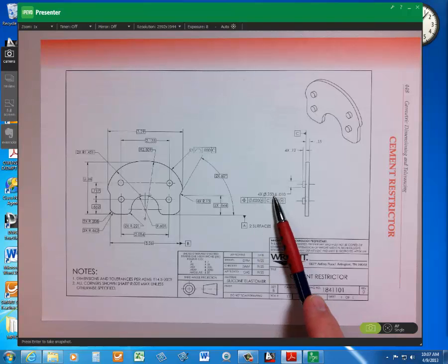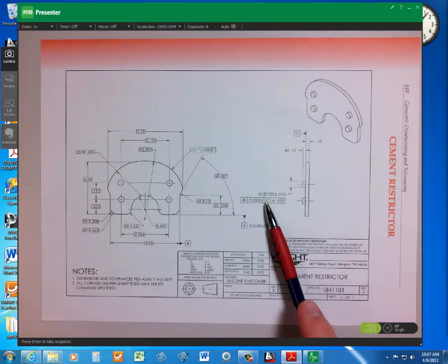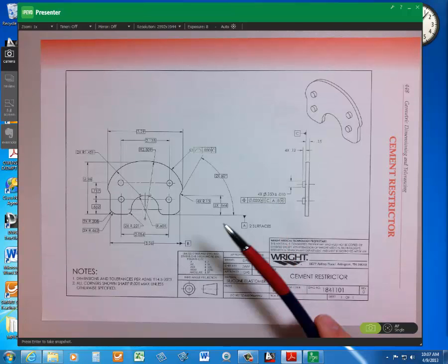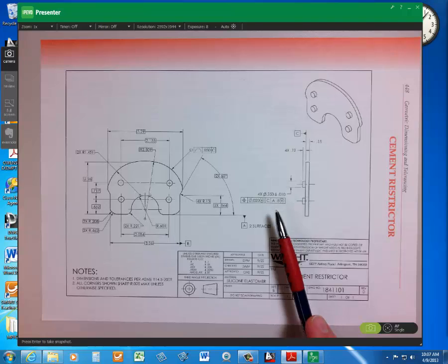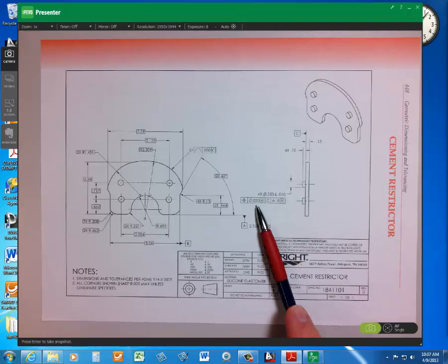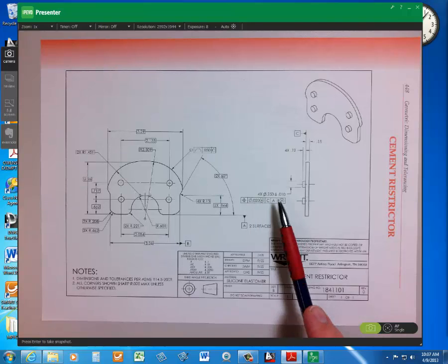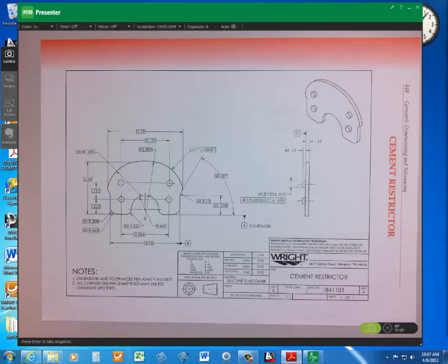Okay, because you're going from MMC to LMC in this case. So at LMC, 0.240, your position tolerance would be 0.040. At MMC, which is 0.260, it'll be 20 thousandths. Your virtual condition for all three is 0.280. Just add them together.